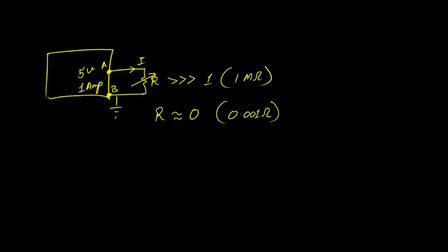Sir, the maximum output current is 1 ampere. So in that case, voltage will drop down. Now the question is, voltage will drop down. The company is giving you the assurance that the power supply will always keep a constant voltage, 5 volt, 1 ampere, right? But when you are connecting a very low resistance, that means almost you are doing this kind of activity, 5 volt, 1 ampere, okay?